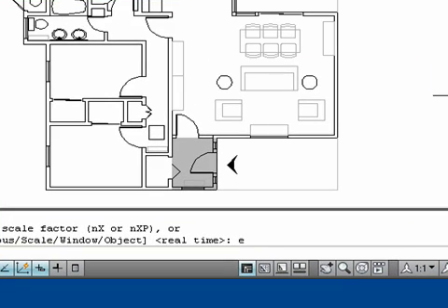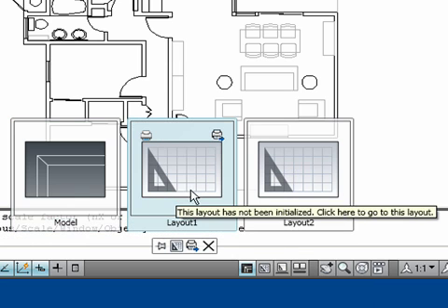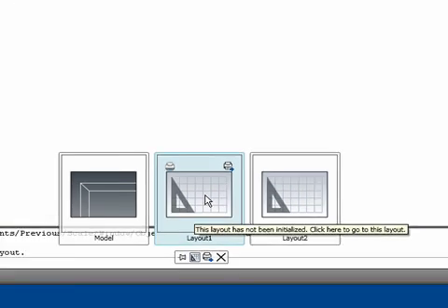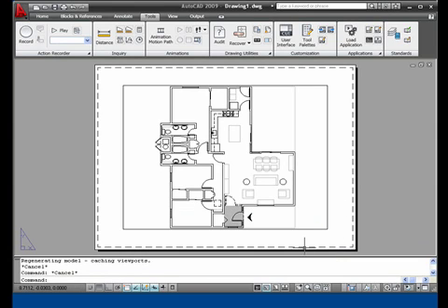Click the Quick View Layout tool in the status bar. You see some preview panels. Click the preview panel labeled Layout 1, then click in the drawing area. Now you are in a layout view. The layout view looks like a print preview. You see a white area representing the paper. The dashed line indicates the printer margin. The solid rectangle is called a viewport and is like a window to your drawing.